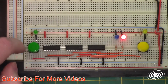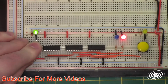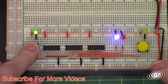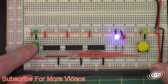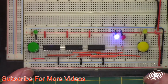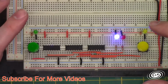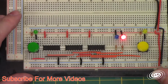So basically I can press data all I want and nothing happens, but if I press data and I hit that enable button, it locks that value in. Now I can press data all I want as long as that enable doesn't go. But here's the thing, if I want to keep it high and the enable's going to go off, I have to hold the button down and then nothing happens. But if I press the enable with this input low, it resets the system.